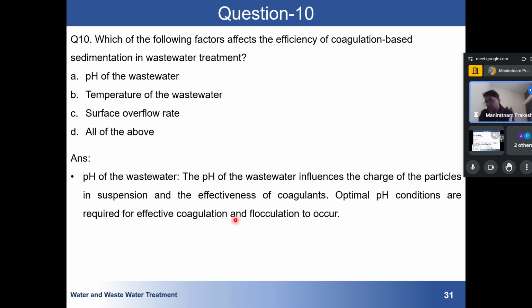So the different types of coagulants that are generally added are alum, then hydrated ferrous sulfate, then chlorinated ferrous sulfate. So we cannot add just any one; you should have an idea of which kind of coagulant you have to add under which condition.